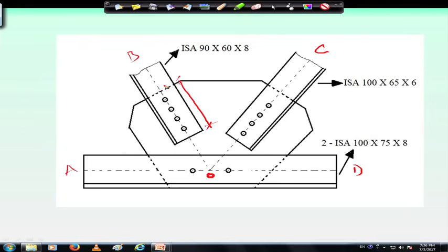we got here as 260 mm, right. So, this will be 260 mm. Similarly, this length also will be 260 mm, because 4 bolts are required for member OC as well, and for member AD we need 2 bolts. Therefore, this length we calculated as 140 mm, right. So, in this way the gusset plate dimensions have been decided, right.